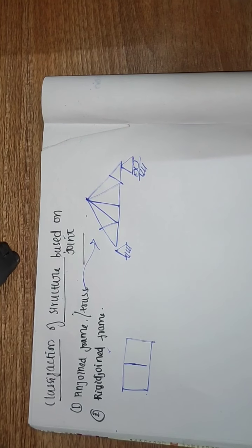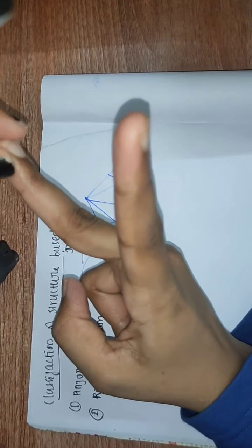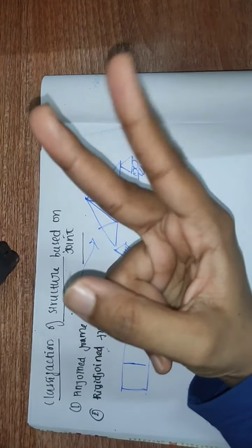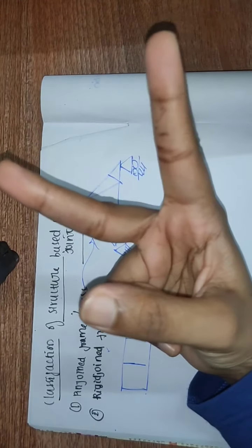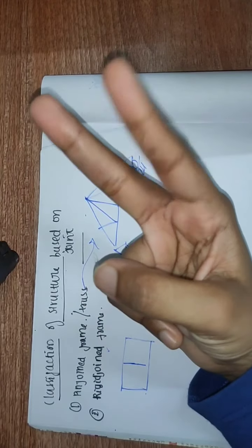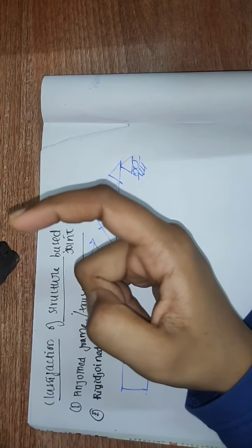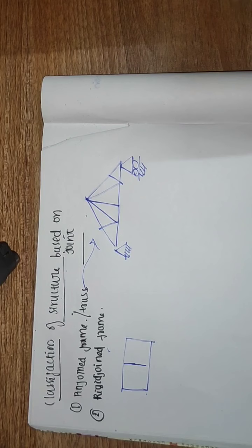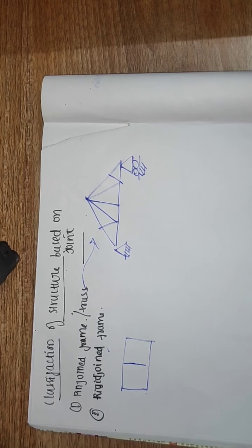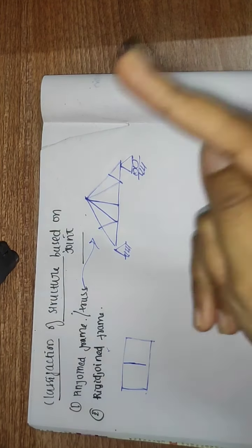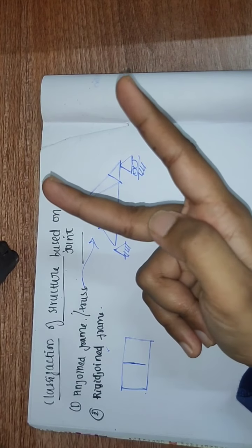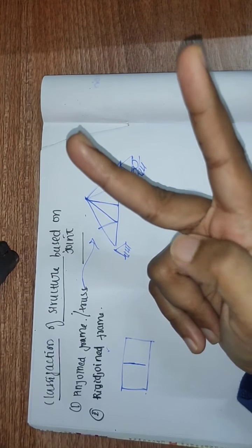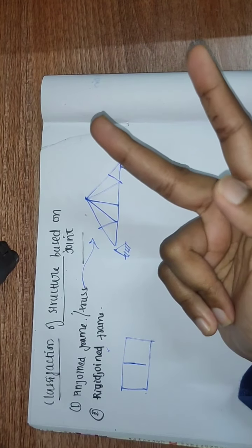If you consider this pin joint, these are the two members, and the rotations in these two members are different. If I apply force on this one, only it will rotate. If I apply force on the other, only that will rotate. Now the members are connected with two bolts or a weld, instead of a single bolt. Next, if I apply a vertical force, it won't move, and even if I give a moment it won't rotate.